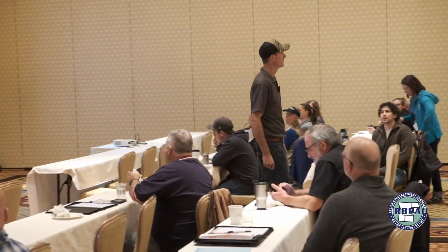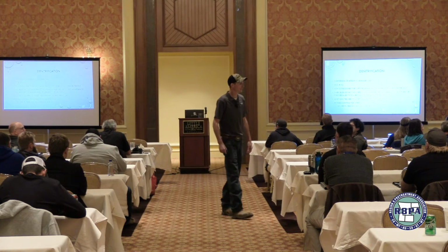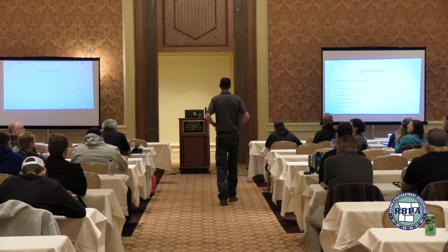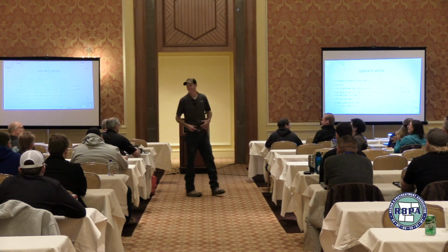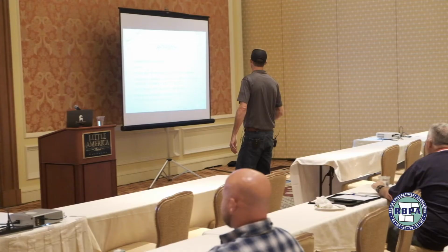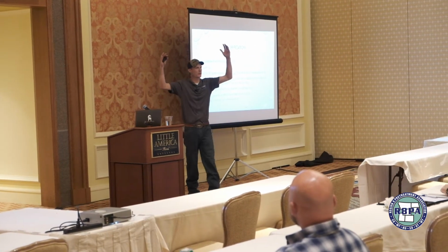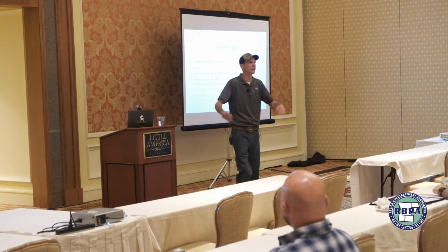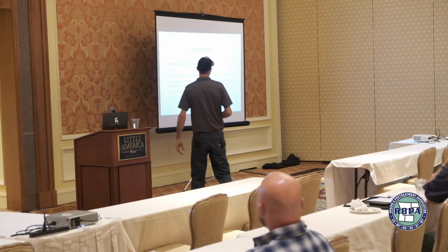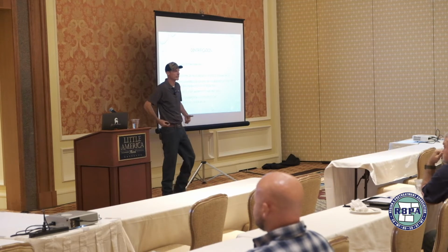I don't know about you guys. If I have a whole bunch of sugar, a whole bunch of prime ribs, and then they take the prime ribs away from me, I sit around for a little bit, get the bubble guts, then what? Nitrogen gas, baby. Okay. So in simple terms: shut the air off. Nitrify, get that ammonia to nitrate, shut the air off, get the nitrate consumed in a cell wall, let them off gas. When there's not enough free oxygen to consume, they will select NO3 as a form of food because it's soluble, easy to get into that cell wall.